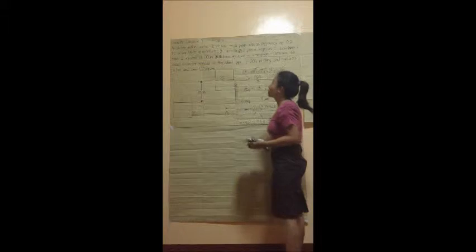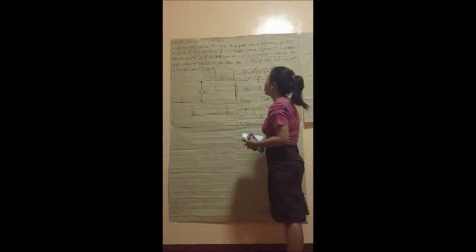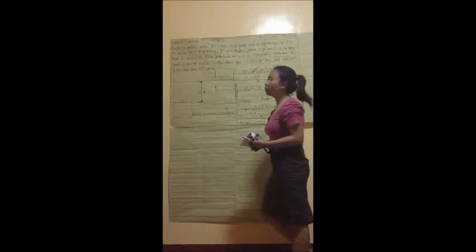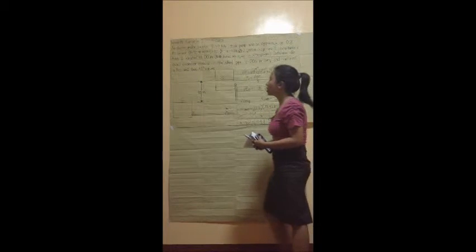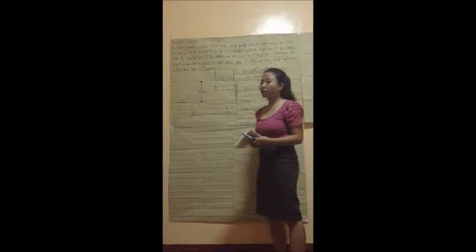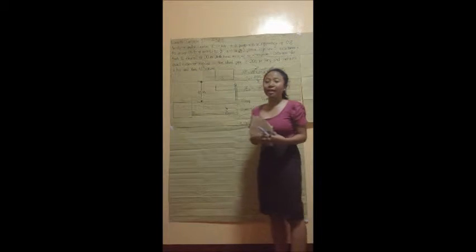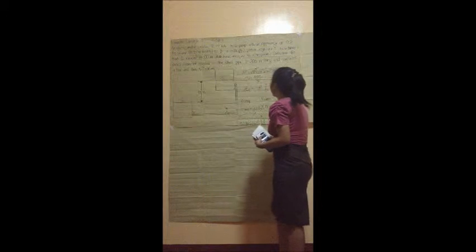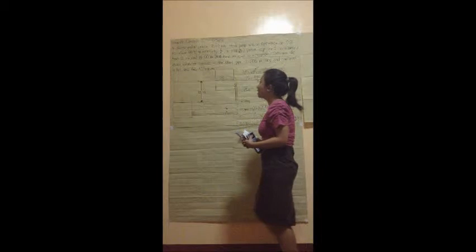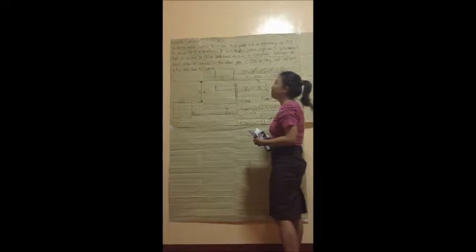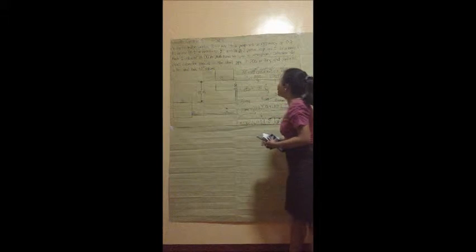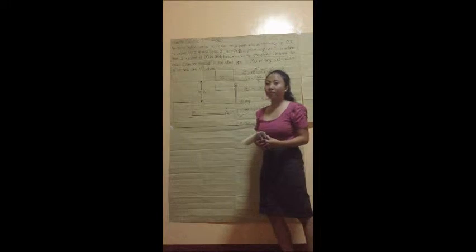An electric motor supplies 70.42 kilowatts to a pump with an efficiency of 0.8 to deliver 50 liters per second of water from a large tank 1 to a large tank 2 elevated at 100 meters. Note that both tanks are open to atmosphere. Determine the exact diameter needed if the steel pipe is 200 meters long and contains a T and two 45-degree